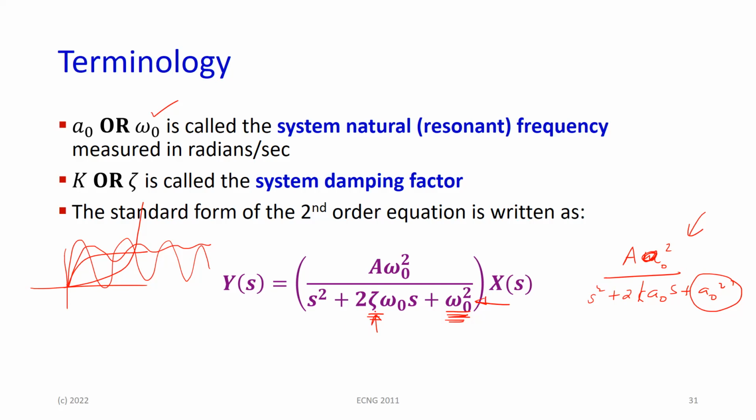If the damping is too large, the system will behave almost like a first order system. Depending on the value of the damping, you can get the response to have a certain amount of overshoot all the way up to oscillating on a continuous basis. In many cases, you have some control over the damping. In other cases, you have to do other things that you'll meet in your controls course, how to compensate for that.